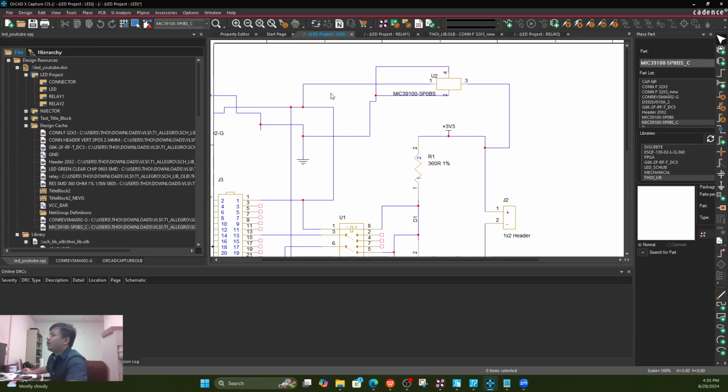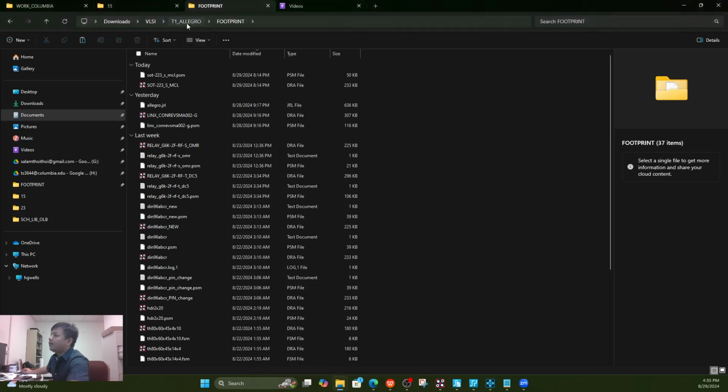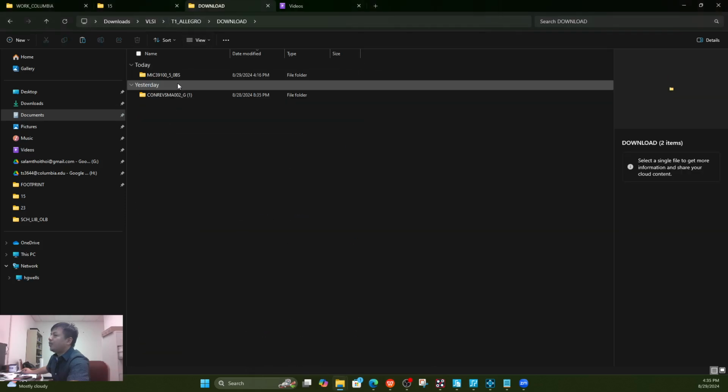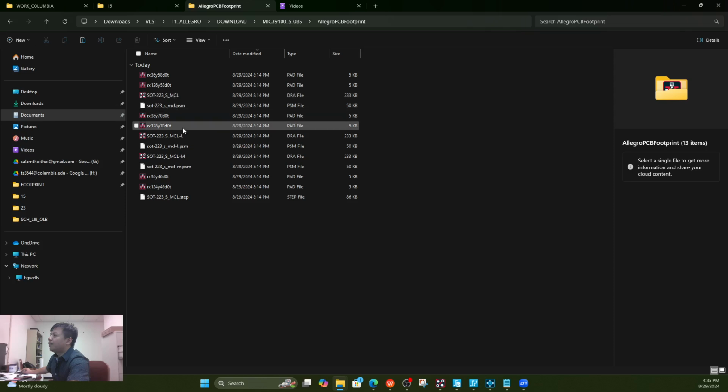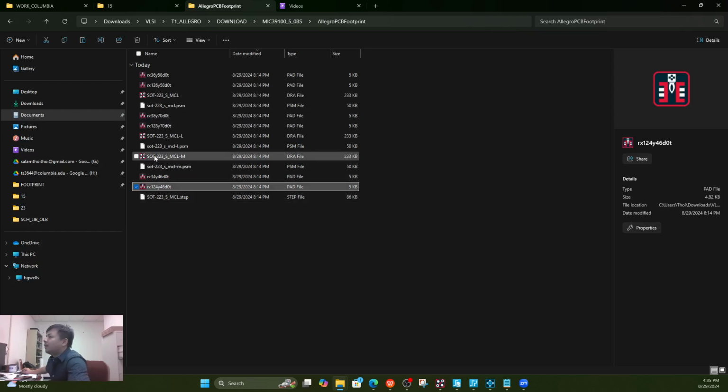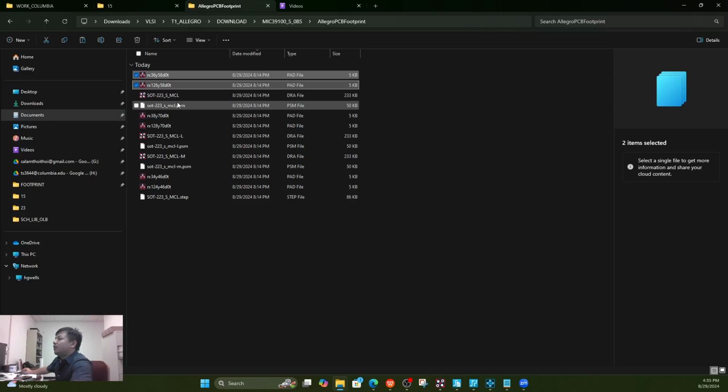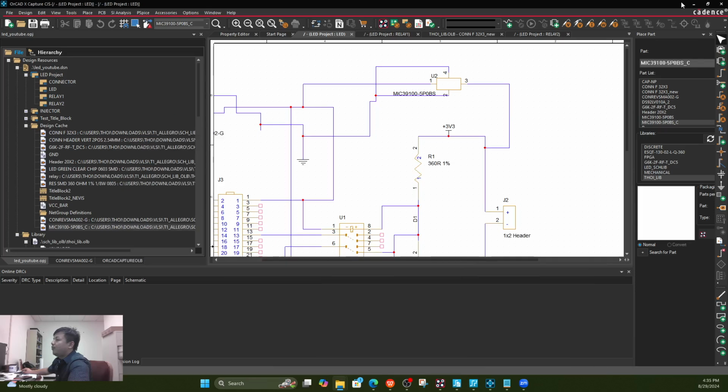Okay, the next thing what I'm going to do, I'm still yet to copy the pad file. This, and this. Most probably this and this because these two might be used over here. So I'm going to copy these two only. But yeah, let's see before doing that. Let us see what error pops. So we have included the footprint. The warning is gone.